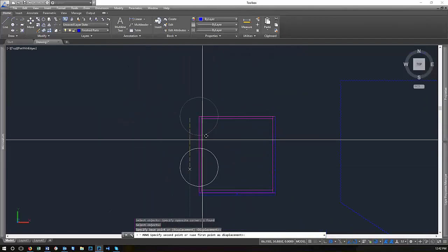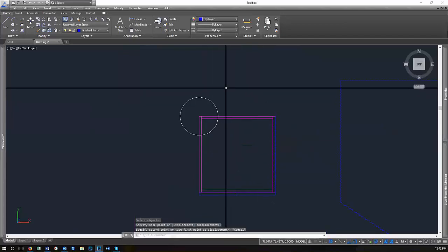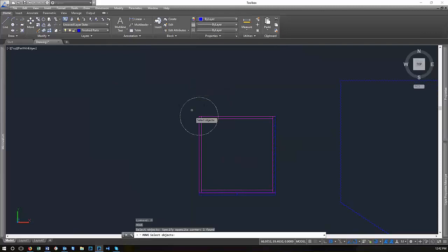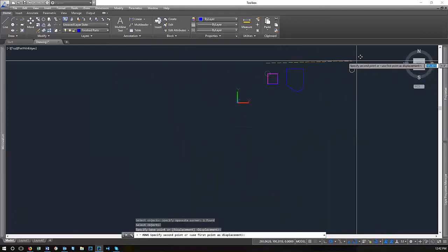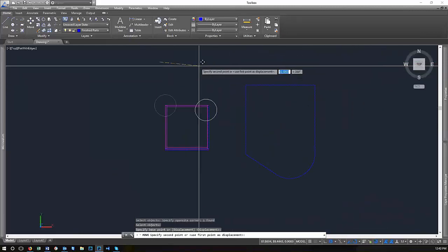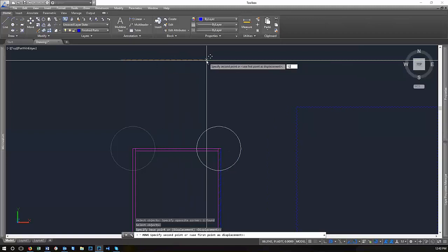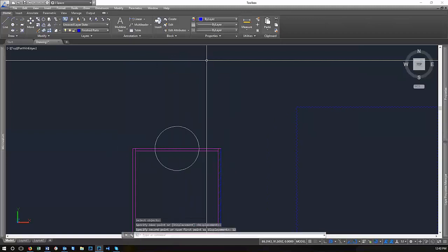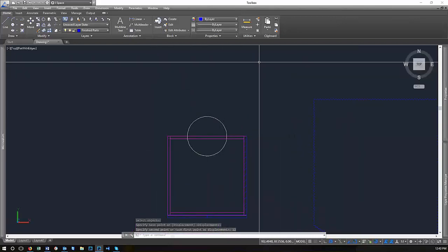It applies much more to busier drawings, but in this case, still, you can use the move command and then click somewhere out here where I can move for days over this direction, and I'm not going to run into anything. It just makes it a whole lot clearer because I'm moving over, and I just want to move it over 12 inches. So enter.